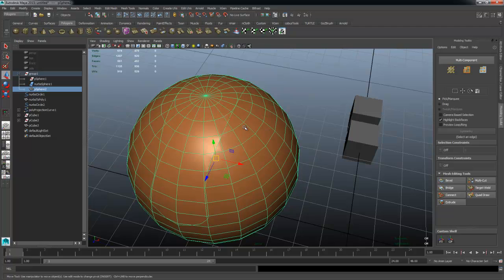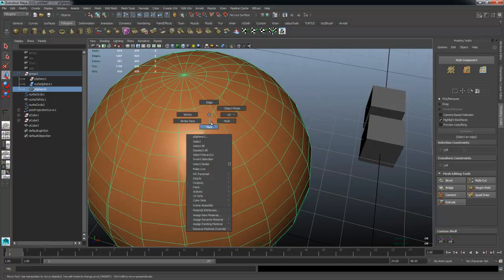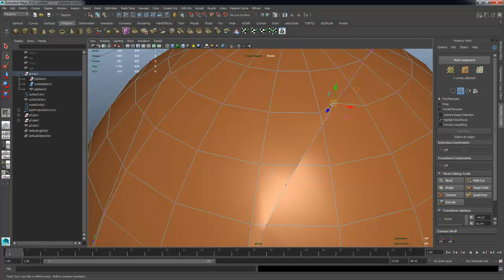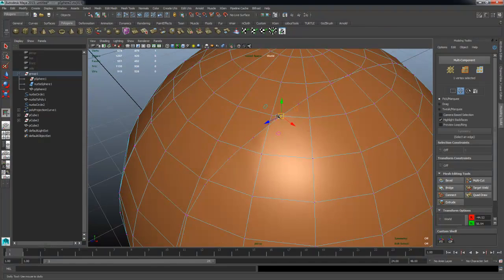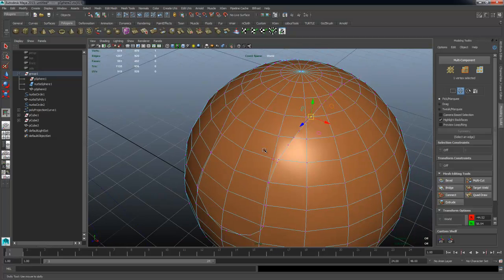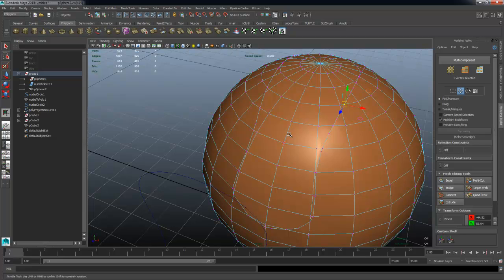In this case, what we've done is Maya has gone into this process of actually projecting the curve onto the mesh, and then taking the projected curve, cutting up the model, and then keeping it in a combined state. So it's not detaching it as two separate shapes. It's still one shape, but if you look at the actual components, if I were to grab this edge and I move it out, you'll see that it's still combined as one shape. If you want to detach it, you'll have to go through this process of selecting the components that are part of the original projection, and then you need to separate them.